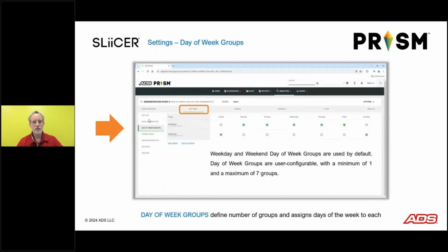Now, another setting related to dry day flows is the day of week groups. By default, we use weekday and weekend groups. You'll find that that works best for, I'll say, 95 to 99% of the work you'll do in I&I studies. But I want to show you that you do have the flexibility to change that.